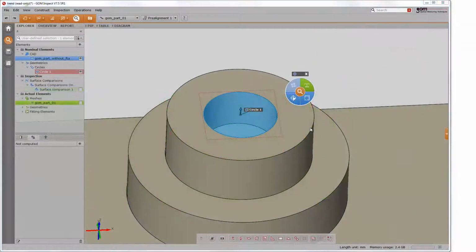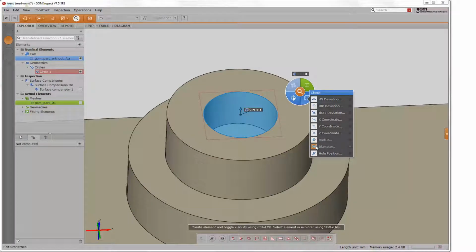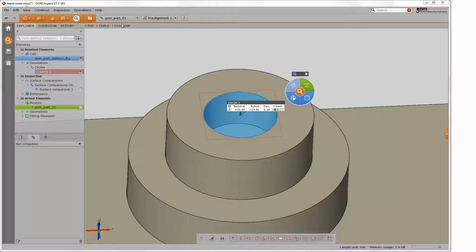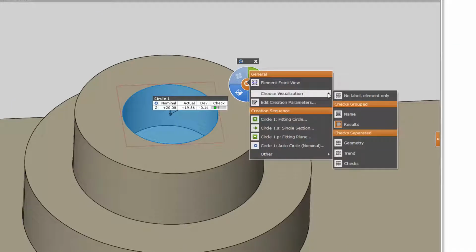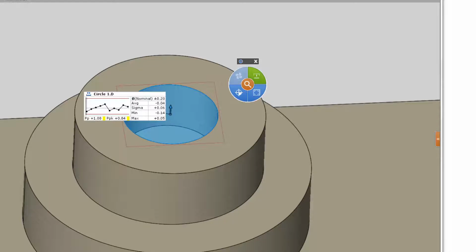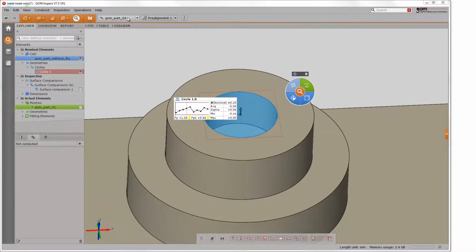It is also possible to extend your inspection at any point, such as the inspection of a circle regarding its diameter. Any inspection will be then recalculated for all stages automatically. You can now change the stages and get the results displayed immediately. In addition, you may change the label template over the Edit button of iInspect in order to display tendencies.